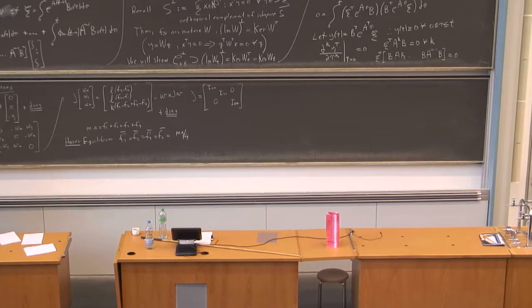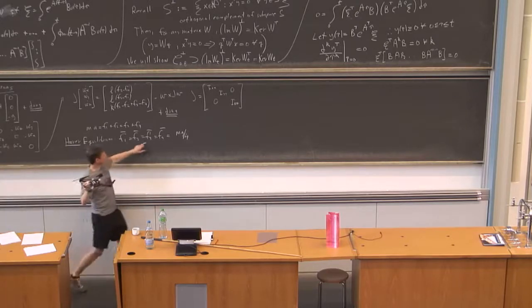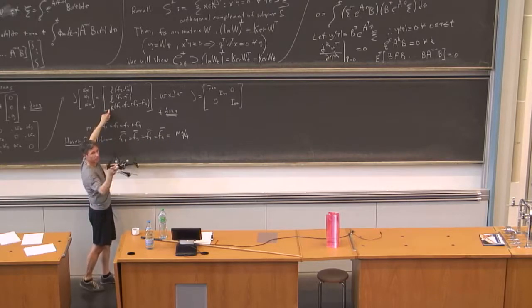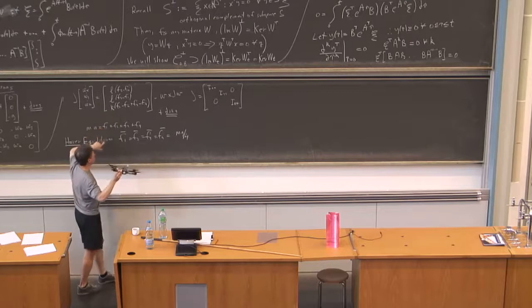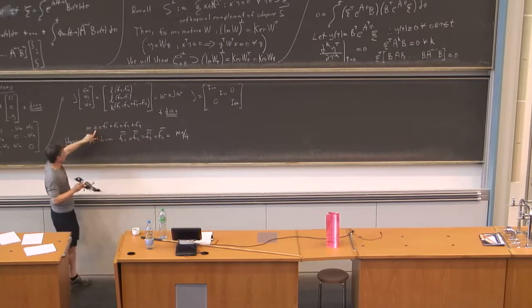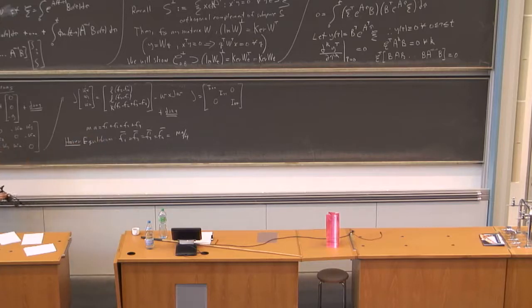There's a yaw angle, but let's not worry too much about that. This is when these forces are all the same, all of these terms go to 0, meaning there are no net torques applied on the device, and the fact that they all sum up to mg means that a is equal to g, and it exactly cancels out g here, which allows it to stay in equilibrium.